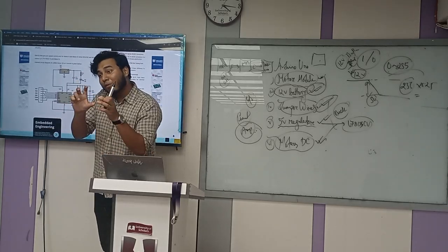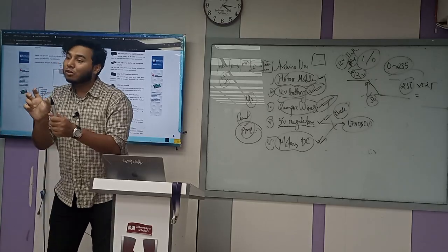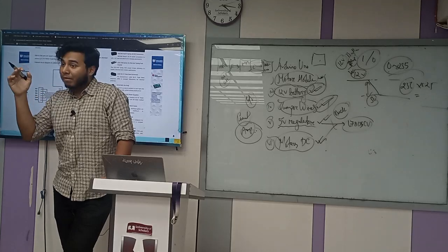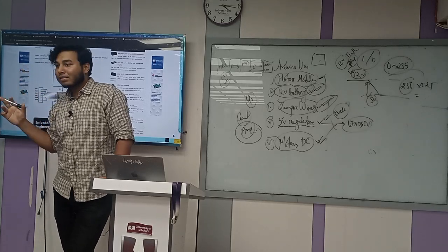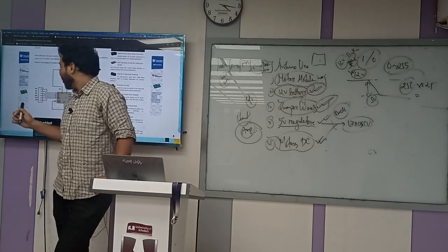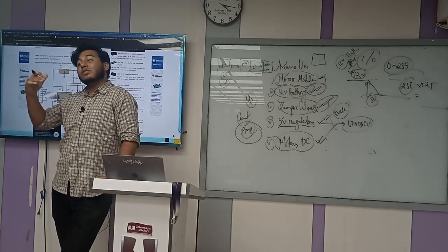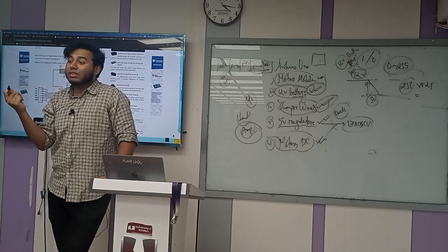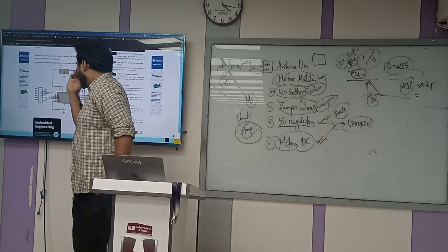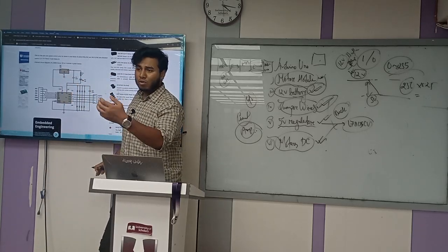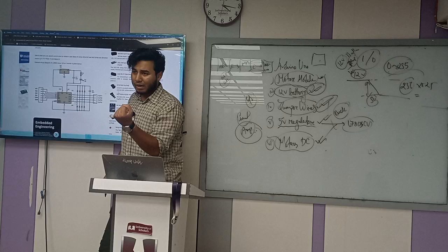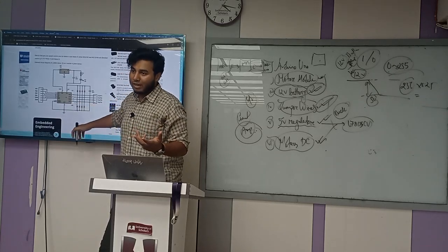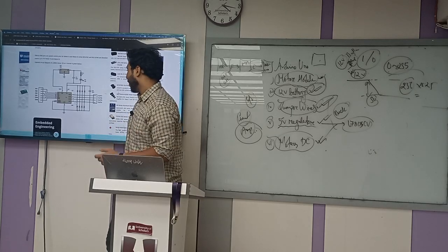So the prices vary just because of the ampere rate. If you have a motor driver with a limit of 10 ampere, it means you can easily pass 8, 9, 10 ampere through this driver, and that comes to the price range because there is a better IC and a better heatsink over there. A very small motor consumes a lower amount of current, so it will be easily workable. You get my point? Fine.